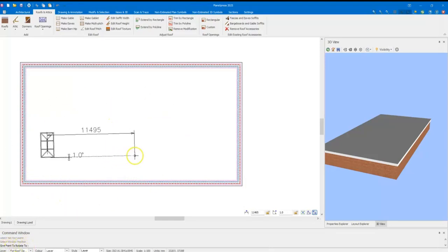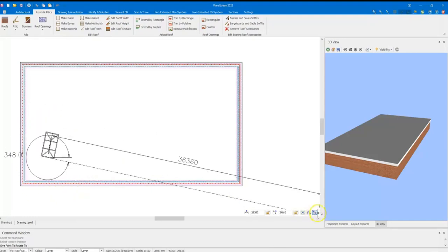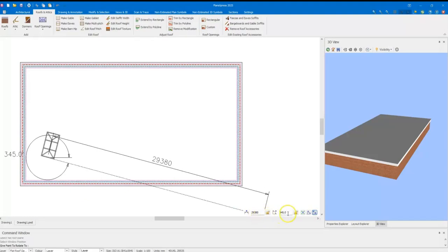I'll just pick a place and we can click on the mouse button, and now you can set the rotation. You see give point to rotate to, so we can rotate freely. Or you can hold shift and lock the rotation in at 45 degrees. We can also use the distance and angle coordinator bar. Down here, the distance is irrelevant for this.